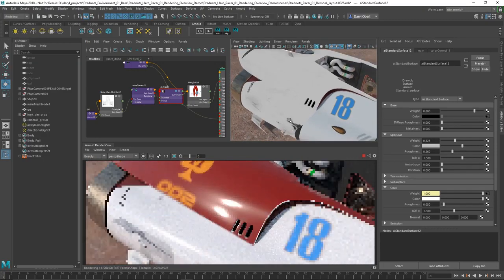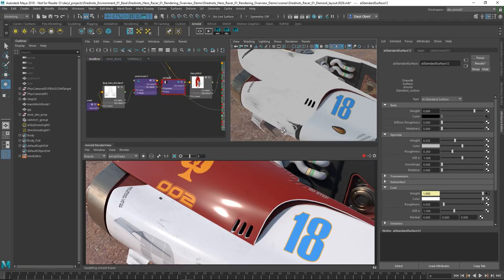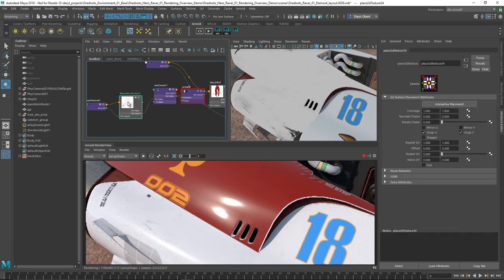And what we want to do is refine the overall roughness of this piece of geometry on that clear coat from a low value to a high value to get those scratches to show up a bit more. So you'll notice that 0.05 to 0.4 is the range that we were using. Where there's dark areas, we want a very broad highlight, and where there's light areas, we want a very tight highlight. So we need to inverse the color range of this map.